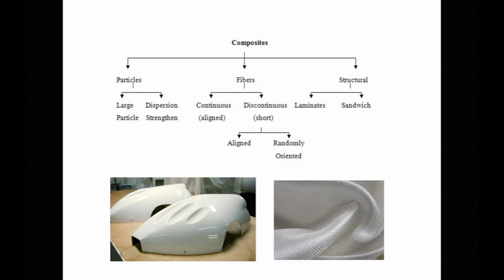You know, think about replacing metals that are used in aircraft. So carbon fiber or glass fiber or other types of silicate, aluminum silicate composites. So this is what we're talking about when we mention composites. So ceramics and glass materials are basically grounded into particles, which you can disperse, and that particle can produce more density on a material or prevent stress crack propagation.